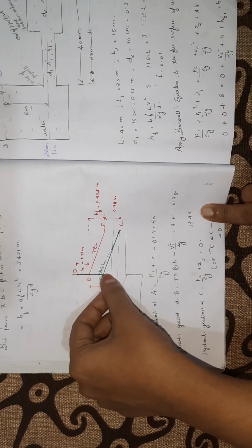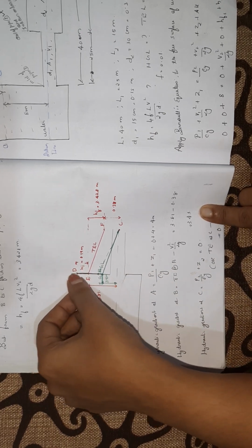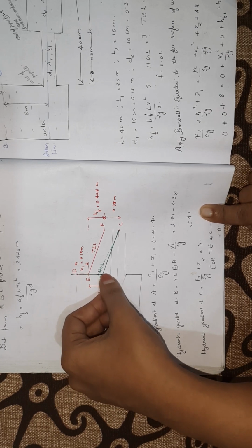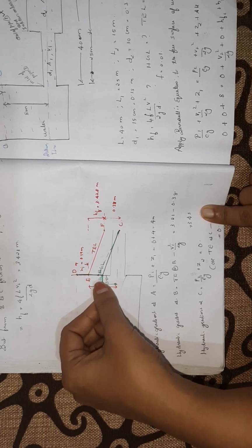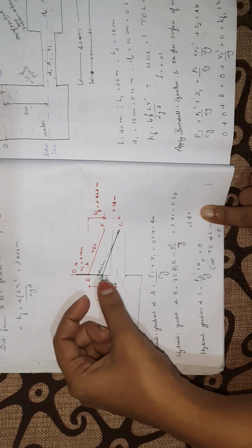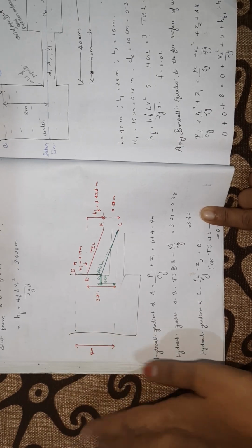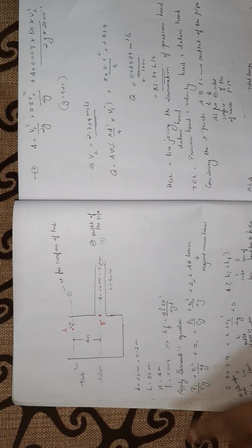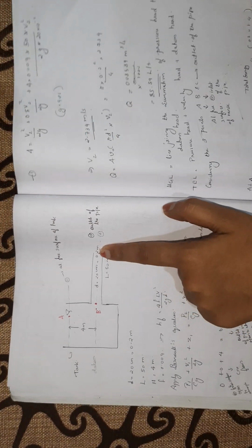So there is a drop, isn't it? Hydraulic gradient was 4 here, and then due to all the losses and subtracting the velocity head, there is a drop of hydraulic gradient. And how much is that? From the center it is 3.43. And what else? We have to compute the hydraulic gradient at the outlet of the pipe also, isn't it?